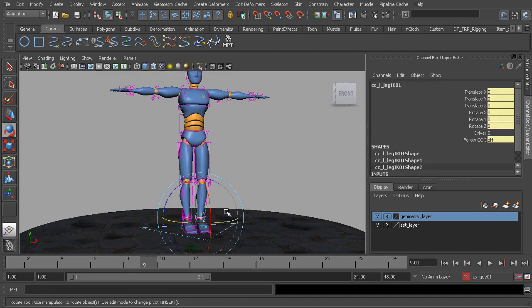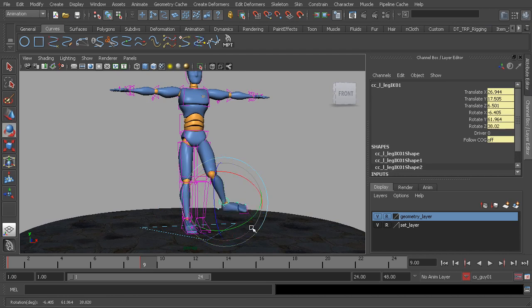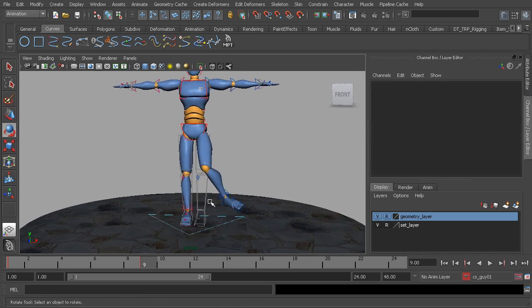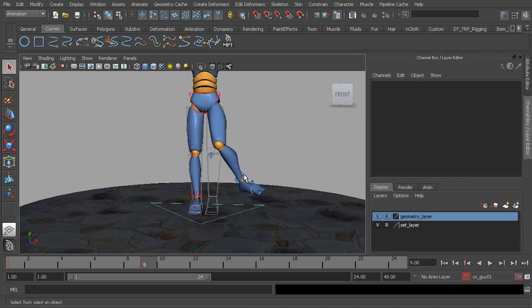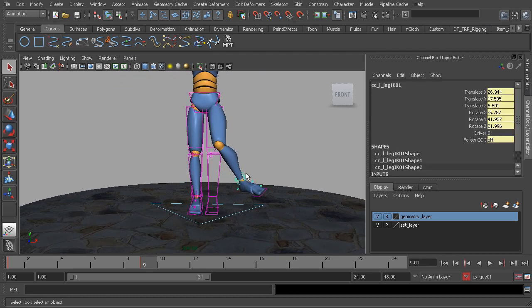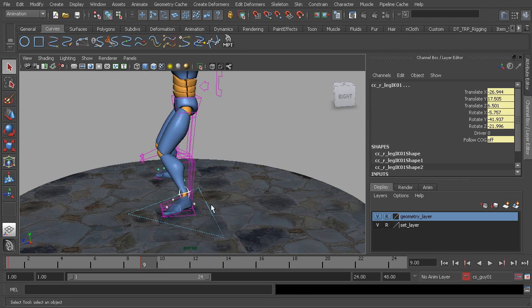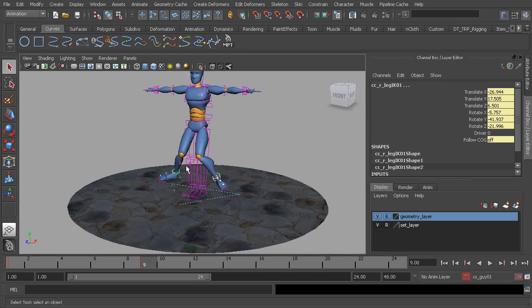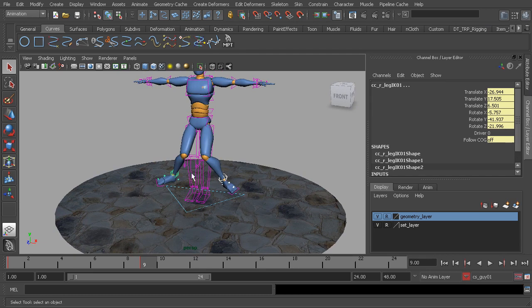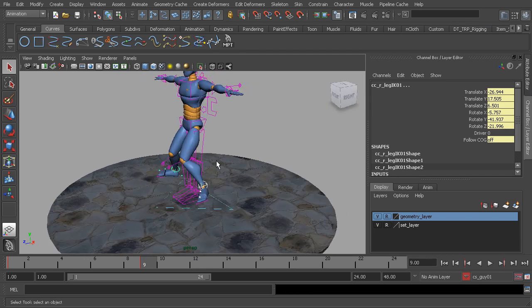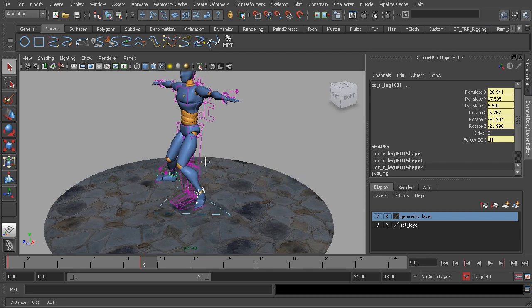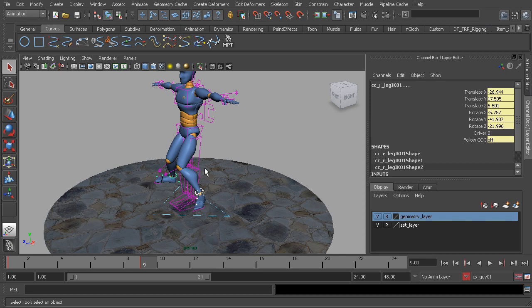If I were to go ahead and move the leg and rotate it over, if we wanted the same pose on the right side, if we wanted it to be mirrored, it'd be just a matter of going in and selecting the source and then shift selecting our target and using our tool. You can see instantly the pose has been mirrored. The limitations with this is that our character must be centered here. Again, this is only for world controls, and since that's the case for our IK legs, just want to make sure that this is used for things like run cycles or walk cycles, or if the character is just going to stay at the origin, this is going to be great to use for that.